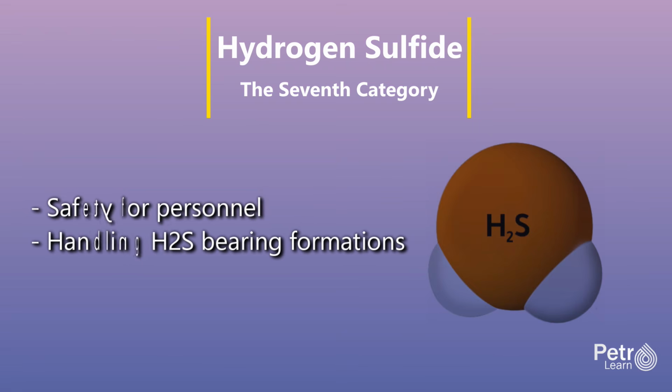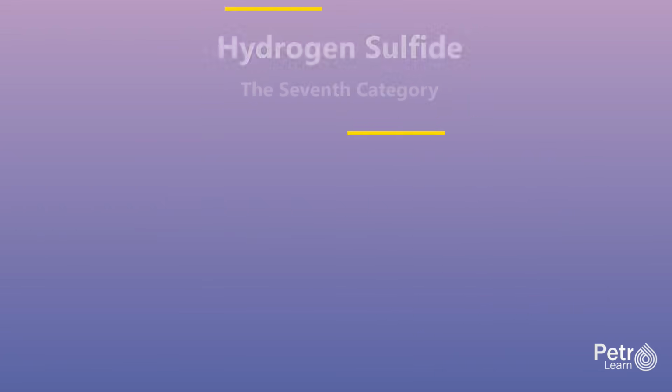When drilling through H2S bearing formations, the drilling fluid is treated with scavengers, chemicals that react with and neutralize H2S, such as zinc oxide, zinc carbonate, or various organic compounds. Specialized metallurgy is required for drill string, casing, and wellhead components because H2S causes sulfide stress cracking, a form of embrittlement that can cause sudden failure of high-strength steels. Sour service-rated materials with restricted hardness and specified compositions must be used in H2S environments.